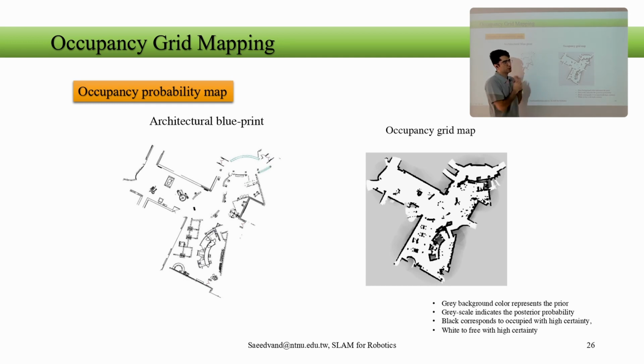We brought it into the form of Bayes filter, and we saw that in probability form we have a problem that is not stable mathematically. To bring it more stable, we apply log-odds form. Then we adopted the inverse observation model on that, visibly seeing what's happening. Then we achieved this map over here.